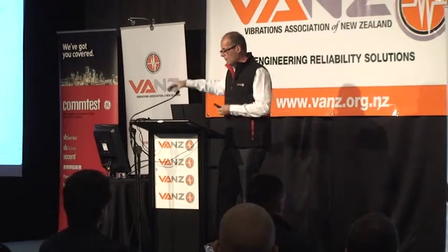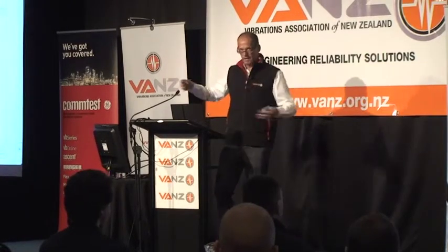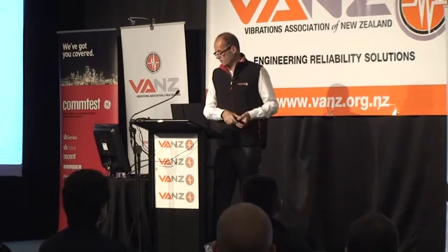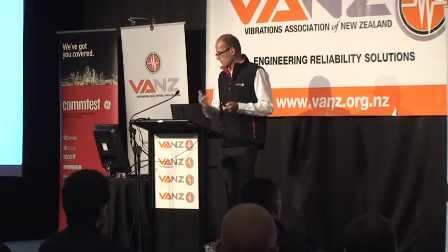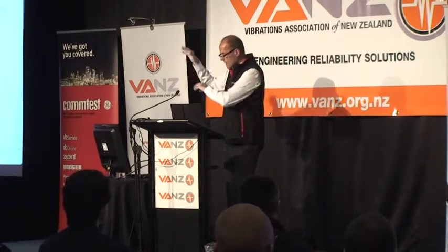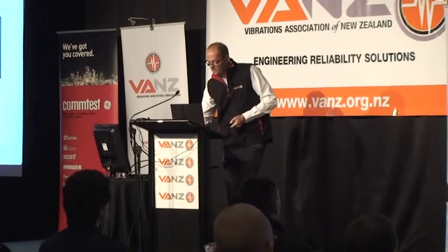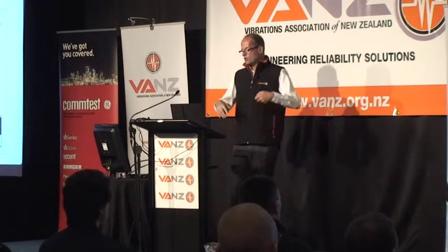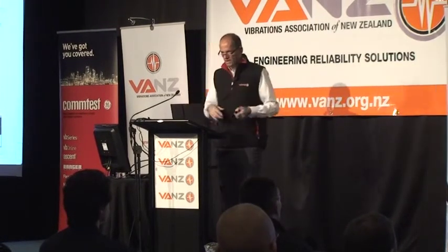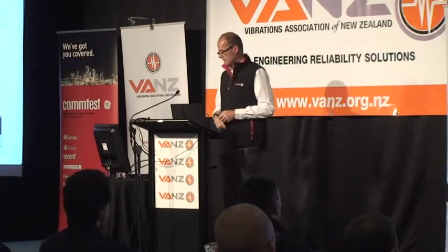If you see a time waveform that's just a whole lot of blue like that, that just means go look at the spectrum. That is actually that same gearbox when it's healthy. And okay, it looks a bit jaggedy and so on, but that's this stuff in here, actually. Anyway, there's also a technique we can use, phase analysis.